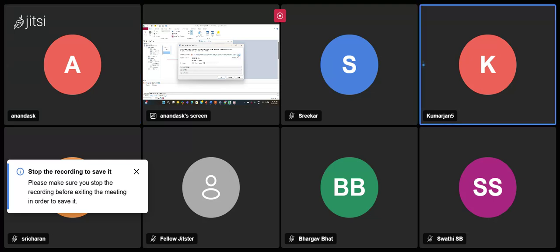The BLF, it will compress more data, and you will not have much usage of your system hardware. If you use ASCII, it will have more data and probably you may end up with fully occupied hard disk space, so there will be no space at all. So normally they go with BLF file because then you can also convert from BLF to ASCII, which is there in that tools menu. I mean, they can do a lot of things on that. So BLF is the one where you can have more data when you go for offline simulation.